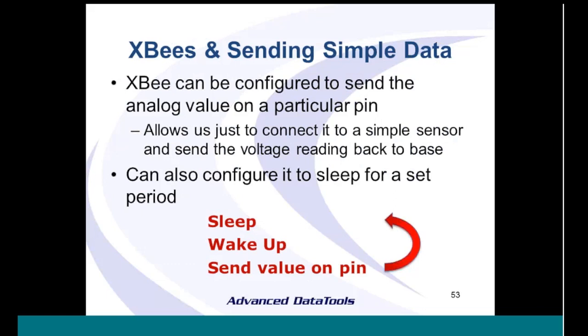Because we can then send the radio to sleep for a while, it can run on batteries and last much longer. We can't use it to do anything too complicated. But for sending simple temperature data, or simple sensor data, that's the way to go.